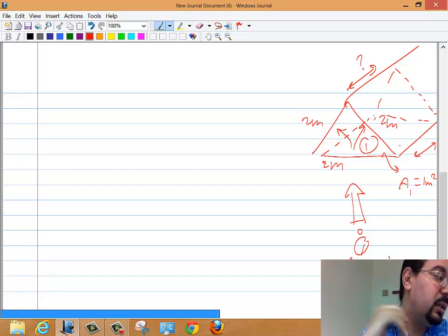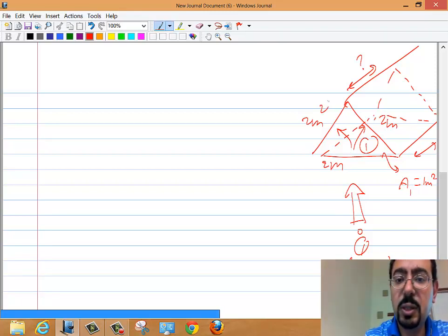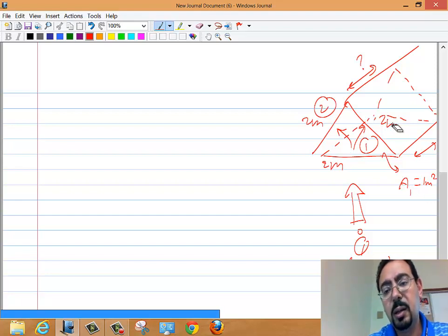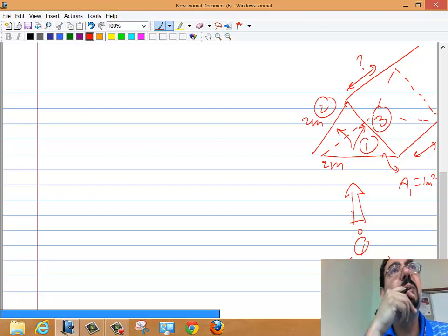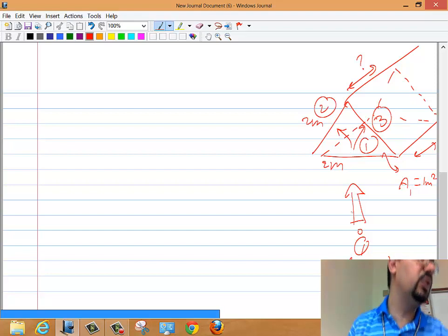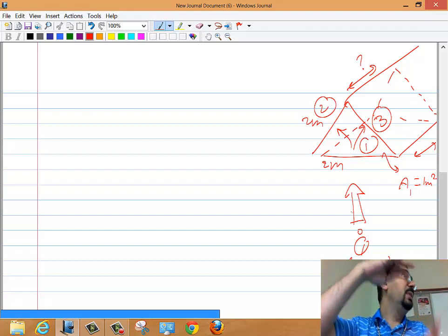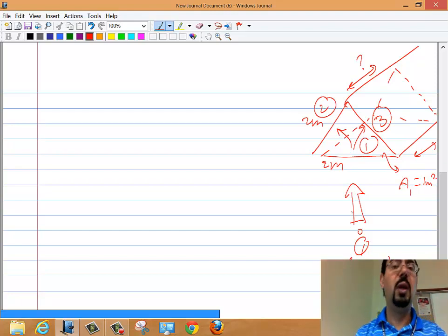And so he said that the side surfaces have emissivity 0.4. So this is called 2. And should we actually call this 3? Or should we call it 2 also? It's 2 because it's a symmetrical triangle, they are the same. And also in the hint there was a statement saying this geometry can be treated as a 2 surface enclosure. He's basically telling you, because of the symmetry, it's basically a base and a kind of roof.